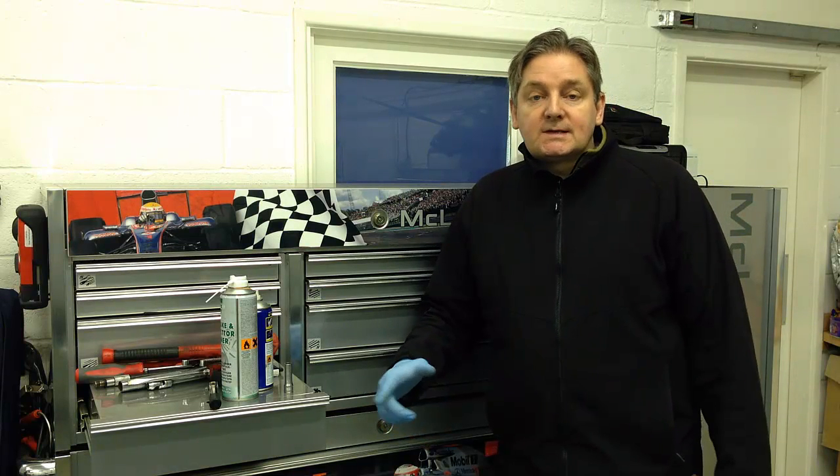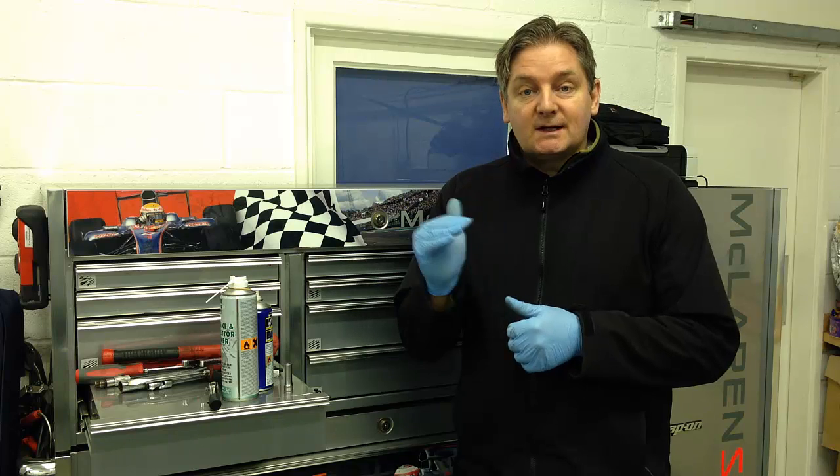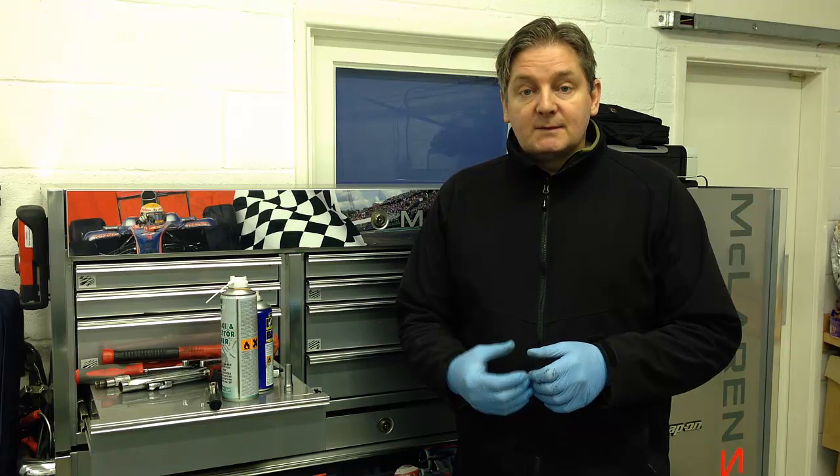This morning we're going to take a quick look at an Audi A4 case study that's in for some repairs. The car has some odd behaviour with interior electrics: lights, wipers and indicators aren't functioning correctly. The car has been somewhere else before, where they diagnosed a central convenience unit, which lives under the passenger side on the floor. The convenience unit has been replaced, and unfortunately the symptom prevails.